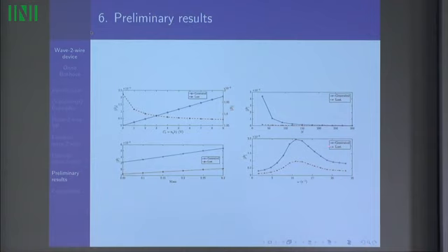And you can also plot the power generated, so that's what you want, the wave energy then generated, and lost is due to heat in the electrical circuit. And that it's plotted here as function of the number of coils, and you can argue that the one coil works best. Here the power is plotted as function of mass.